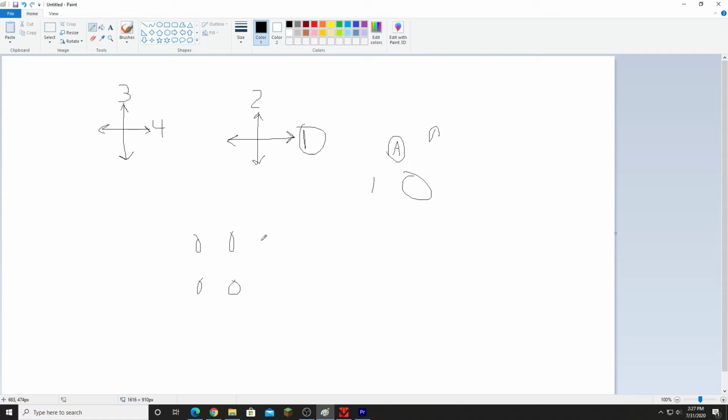So the way it works is this wheel right here wants to go this way, and this one wants to go this way, and they're going to go towards each other, and the robot's going to move this way in this example, and then these want to go away from each other. So this one wants to go that way, and this one wants to go that way. So these two are going the same direction, and these two are going the same direction. So it's like an X right here with the wheels. And it's going to slide this way, and then you just reverse these and make it go the other way.